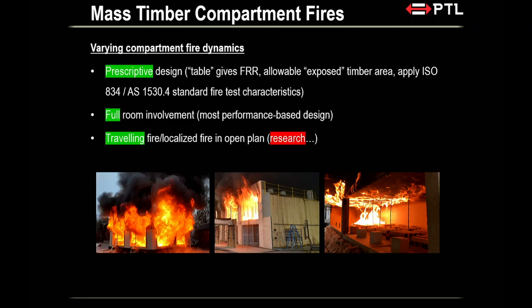But for now, when we consider fire dynamic, have a look at this picture. They might all look like flame to you, but if you look closer, they are different, okay? Most of the time, for my performance-based design, I'm assuming a full room involvement. These two examples are a full room involvement. So basically, the condition inside the room is uniform, 900 degrees Celsius throughout. That's my assumption. I do my calculation that way.